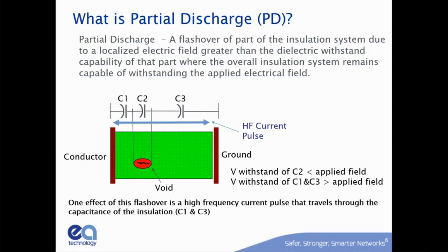Because it's very small capacitances, it's a very fast pulse, very fast rise time, very short decay. They're typically maybe 5 microseconds long total, 5 to 10 at the outside. And they can be in the milliamp or microamp ranges. So it's a real low energy event, but it's a real event. And it's unipolar. When you go one polarity, it's one way, and the other polarity, it's the other way.